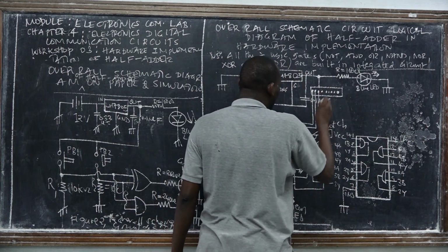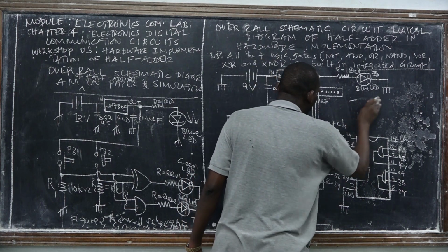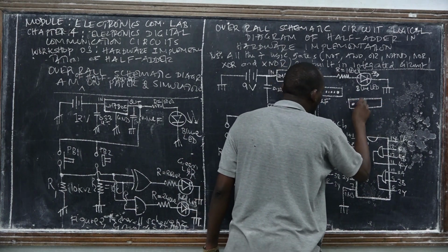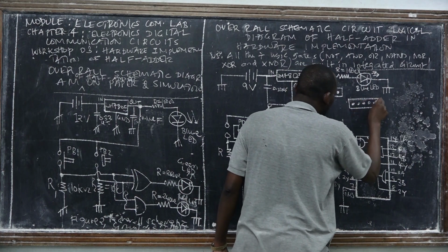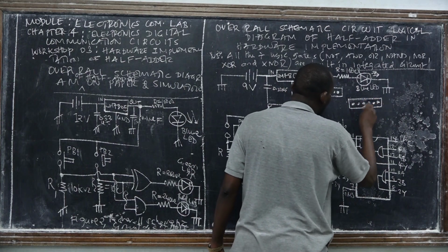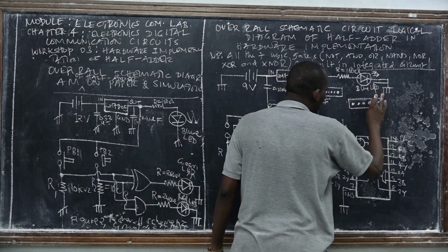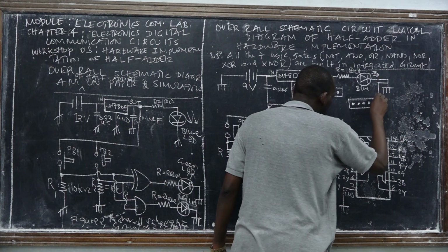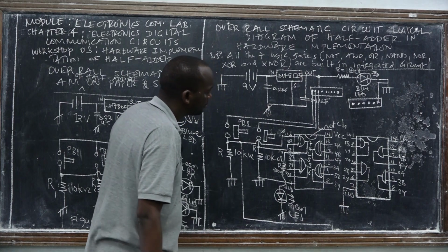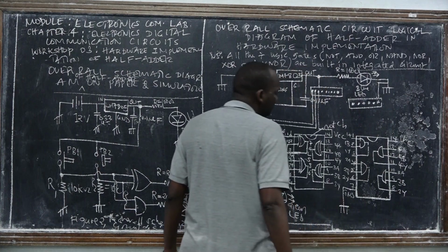And also, remember you'll have a T block for the ground. You must have a T block for the hardware implementation where you'll have all the power rail in case of the breadboard, but in case of the Vero boards and PCB board, you need the T block for the ground and for the common power. So here we have this, we call it the common ground power bank. All of these grounds should be drawn from here.